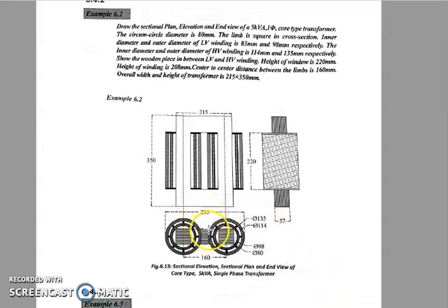Yeah. So now the plan is ready. Now only this elevation is left out. Here there was sectional plan and elevation. Sectional plan means this one, full section. In the previous first example, whichever we had shown, that is something like right half in section. Right half in section means only this much you have to show in detail. Here full hatch you can do and keep. In the later problems you will understand that.